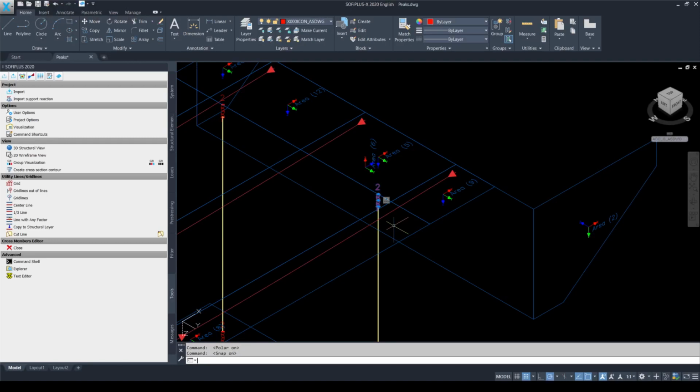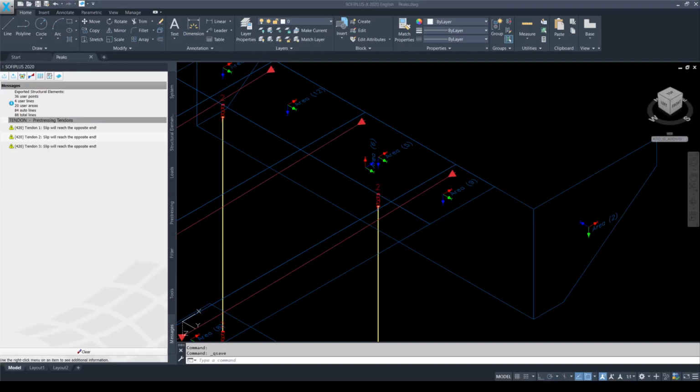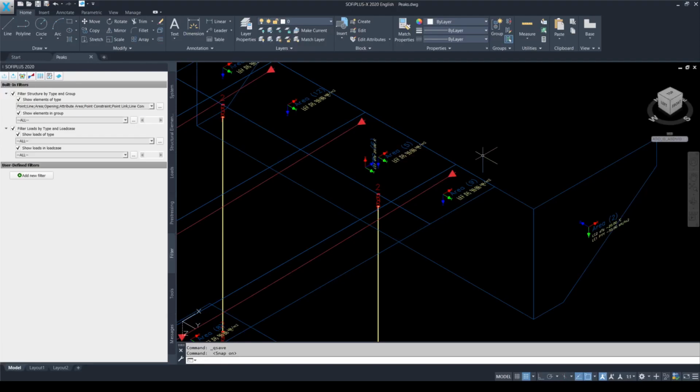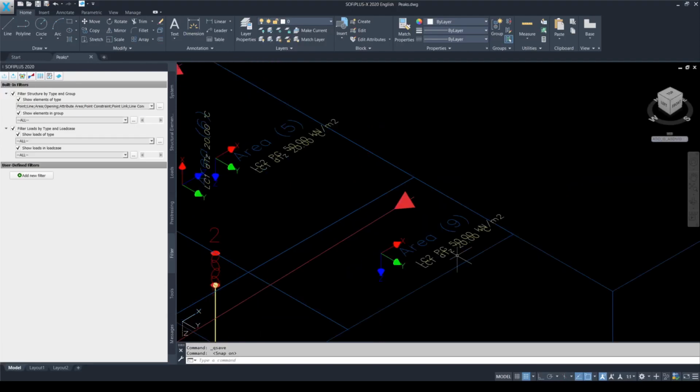And since it's happening in a very small area, namely at a structural point, a singularity will be formed in the bending moments, and the quad elements cannot be designed against these very high bending moments. Let's try it out now. I have generated two load cases.